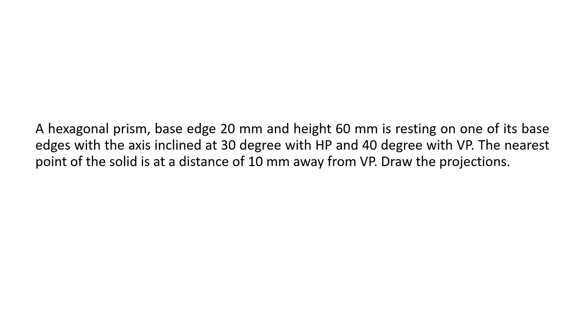Welcome to this video. In this video we'll see a question based on projection of solids. The question is: a hexagonal prism, base of edge 25 mm and height 60 mm, is resting on one of its base edges with axis inclined at 30 degrees with HP and 40 degrees with VP. The nearest point of the solid is at a distance of 10 mm away from VP.